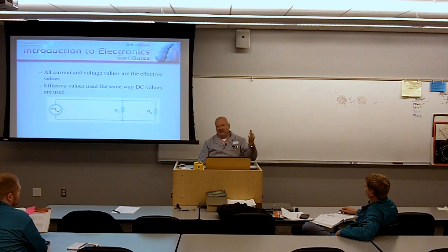Okay. SeaTac Airport, a 757 I just took off, what's the flavor? 400 hertz. Beyond that, a digital multimeter set for AC is pretty much worthless. Not worthless, you could accurately measure probably up to about 1,000 hertz. After 1,000 hertz, the numbers you get are garbage.